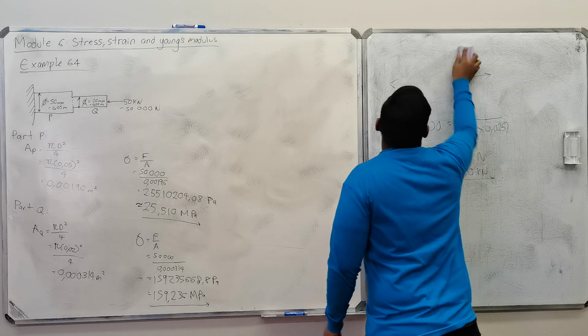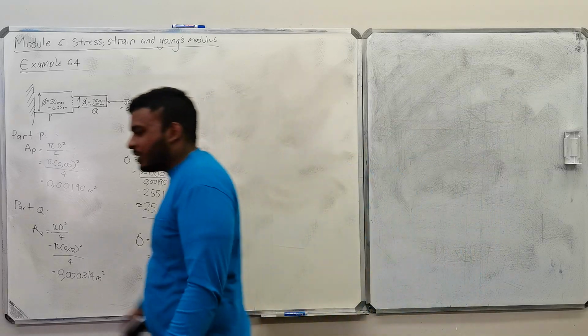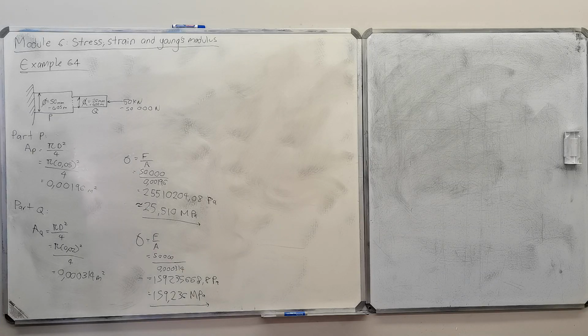Strain is also not difficult. So, direct strain is on the bottom of page 144. They tell you that if the material of an object is subjected to a tensile force or a compressive force, stress is produced in the material and its length is obviously changed. Remember, with a tensile force, it's a pulling force, so whatever its original length was, it will now become longer. With a compressive force, it's more of a squashing force, it's going to become shorter. So an extension of length will take place in the case of a tensile force, and a reduction of length in the case of a compressive force. We all understand that, right?